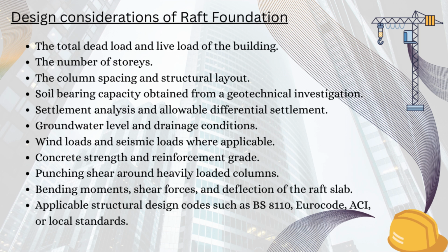Structural design considerations. The dimensions of a raft foundation are never selected by experience or guesswork. Every raft foundation must be designed by a qualified structural engineer based on detailed engineering calculations. The design depends on several important factors, including the total dead load and live load of the building, the number of stories, the column spacing and structural layout, soil-bearing capacity obtained from a geotechnical investigation, settlement analysis and allowable differential